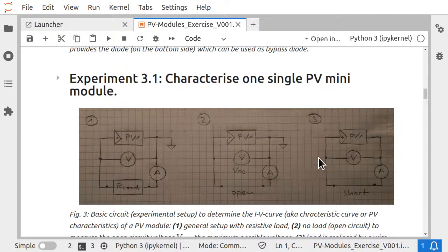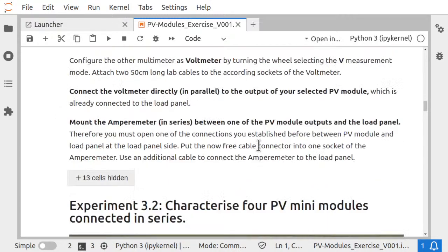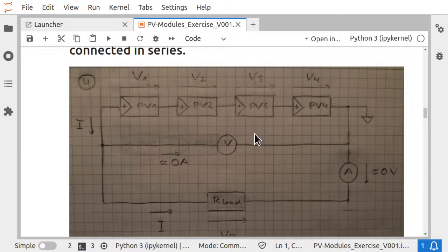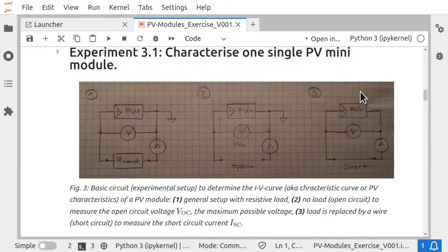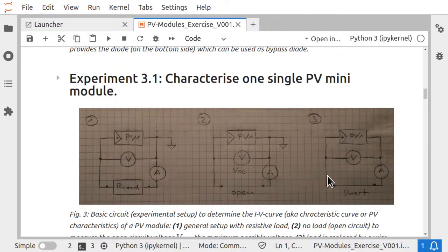So how can you have a voltage difference of 20 volts here if these 2 points are at the same potential? It's a short, right? This is one wire, this is one node, one potential. All of that here is one potential. So what's the potential difference? Of course, 0, right? In fact, you would expect 0 volts, but the wires are not ideal, so there is some resistance here in the wires, right? That means there is a small voltage drop, but it's negligible.